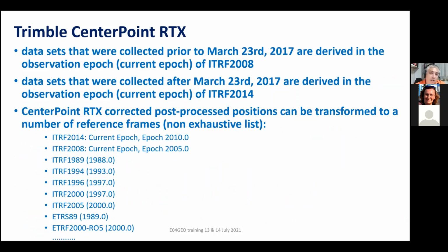Data sets that were collected prior to March 23rd, 2017 are derived in the observation epoch, the current epoch of the ITRF 2008. And if data sets were collected after that date, solutions are derived in the observation epoch, meaning the current epoch of the most recent ITRF 2014. The CenterPoint RTX corrected post-processed positions can be transformed to a number of reference frames. This is a not exhaustive list.